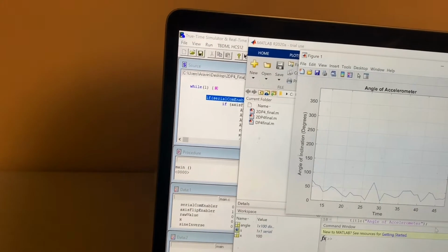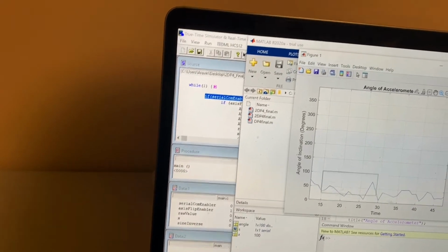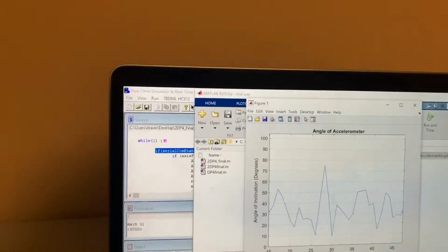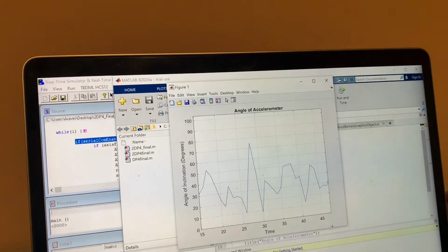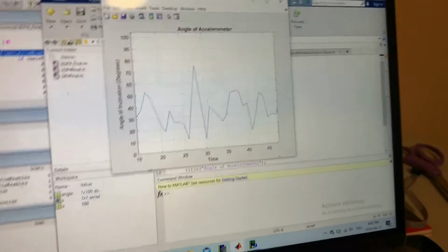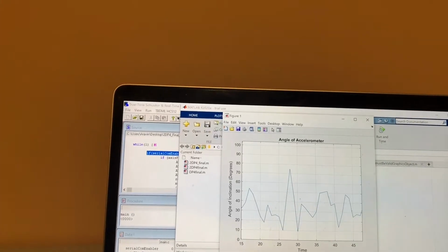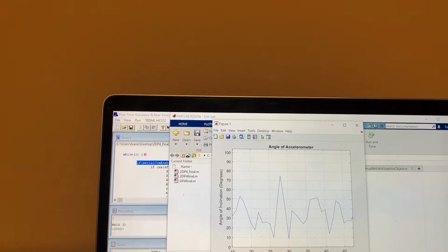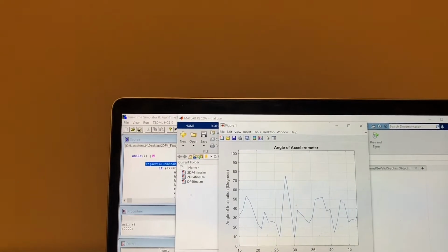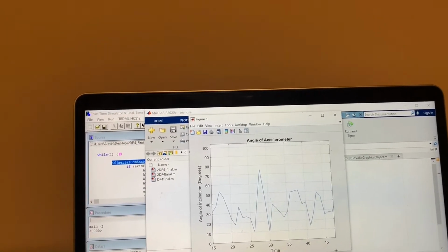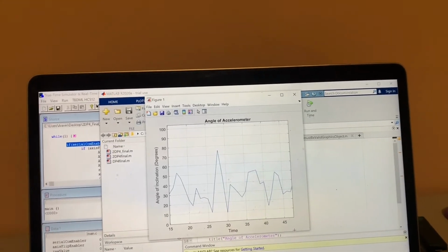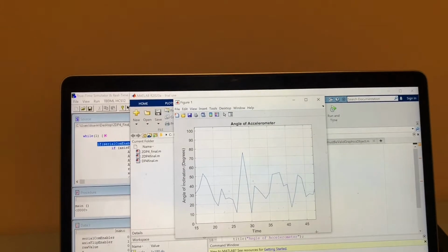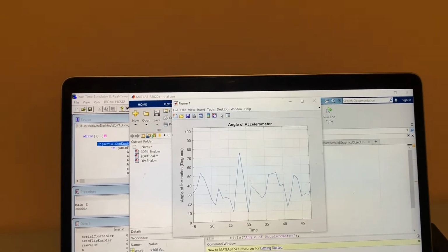As you can see here, we're well within the desired range of 0 to 90. As I mentioned before, the overshoots were because of some noise in my accelerometer, so just potential error initially. Whenever you go beyond 90 degrees, you go well over, and that doesn't work in the linearization formula, so that's why you can see those values coming up. But again, these are the correct values, as I was adjusting the angle accordingly.